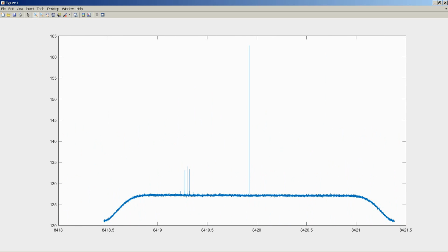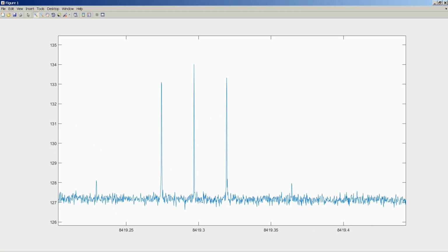And yeah, that's pretty much it. So here is a central peak. This is Voyager, this is Voyager, this is Voyager, and a few other sidebands. The normal frequency signature of a BPSK signal is some sort of sinc shape. So here you would have a main lobe, here you have a side lobe, and we don't really recover this BPSK shape here, because I should probably average the data over 5 minutes. But I guess you got the idea of what to do and how to do it now. But indeed, if you did it, you would see the sinc shape, and you would understand that those peaks signal the presence of the side lobes, and those 3 peaks here signal the presence of the main lobe.